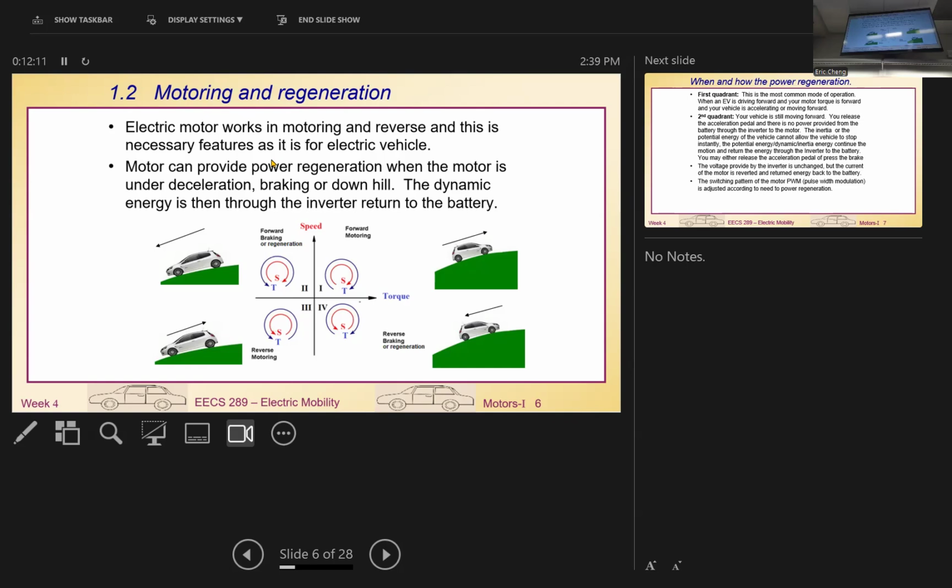So that's why we can still see some kind of braking, due to the energy returning to the battery. But if in this case you don't want that, you want it to just freewheel, you can shut down the battery connection. The vehicle will still go forward without any feeling of braking. Once you connect the battery to braking, we still have the power regeneration due to potential energy delivered downward into the regen.